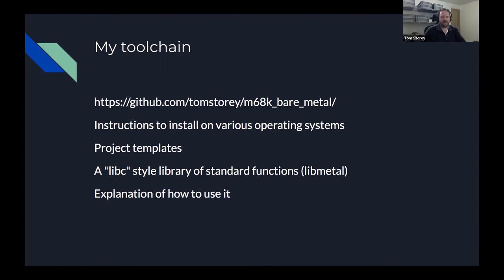There's a couple of project templates, so there's two ways you could compile some code. One is an actual standalone code, which is what I've been doing here. As part of the standalone code, it will generate the exception vector table, because it's probably going to be the thing that goes straight into the ROMs and gets executed by the CPU at startup.